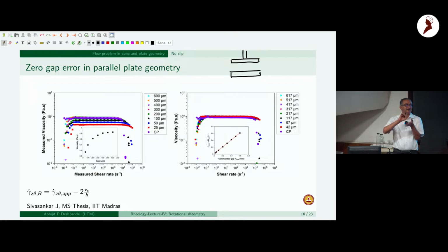Generally we instruct the instrument to go to the 0 gap. The instrument lowers the gap, and because of the air gap between the two, air is eventually squeezed out, the pressure increases and there is a normal force. The instrument senses that, and through its algorithm declares that it has reached the bottom plate.